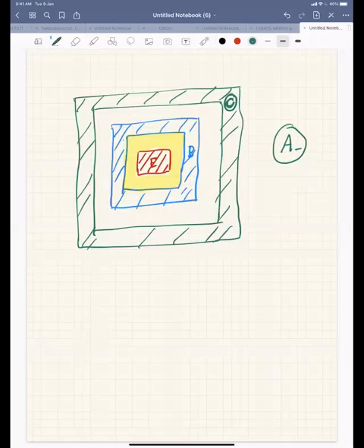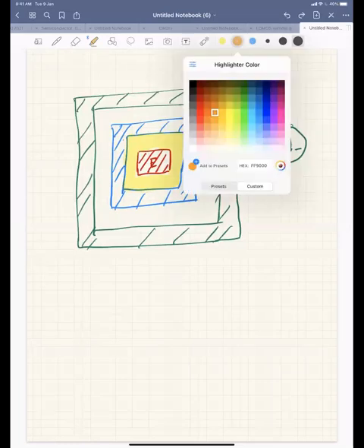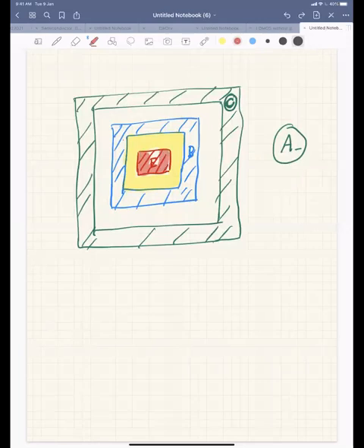The area of your bipolar junction transistor is nothing but the area of your emitter, because if you look from the top, your intrinsic part is this part. Other regions are extrinsic regions of your bipolar junction transistor.